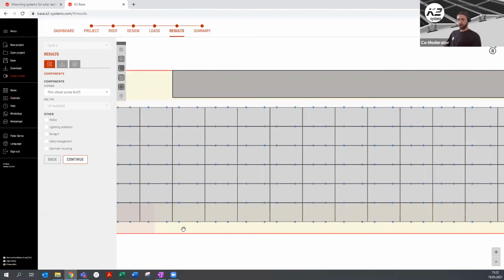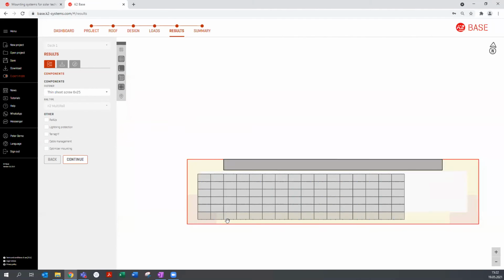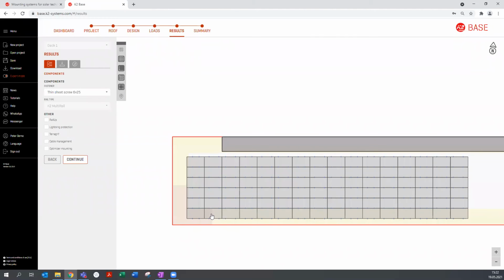And also, just on that, Roman, so we do need a thermal gap in the vertical direction, but just not in this one, right? Is that what you're saying? Because it's just a small roof. Exactly, exactly. We do need one, but just after, I think, 24 meters.